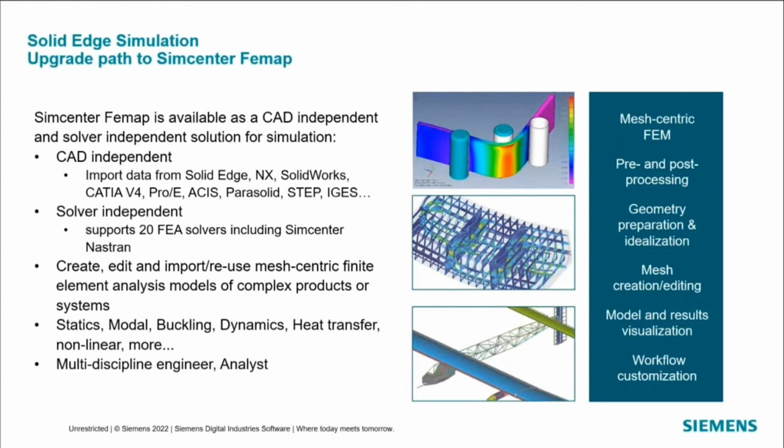The starting point of FE model creation is generally the CAD model, and FEMAP has some extensive functionalities to remove problematic entities, along with CAD model cleanup tools. FEMAP lends itself to a mesh-centric approach to FE modeling and has in-depth tools for mesh creation and editing. And it can work well with orphan meshes for FE model reuse. For plate and beam modeling, visualization tools are important to let you see how the elements appear with plate thicknesses, beam sections, and offsets, etc.